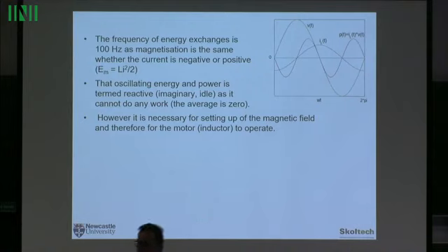If a network is DC, current is constant, so you don't have those exchanges of energy with the coil. The coil will get magnetized and it will stay magnetized. So what does it mean then if you hear, for example, that solar panels produce a lot of reactive power? Is that rubbish? No. That's a complicated argument. The solar panels themselves produce DC power.